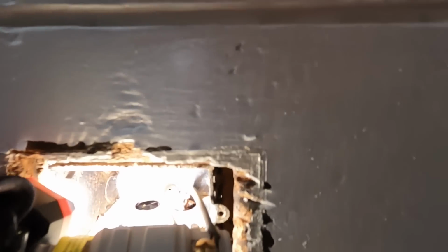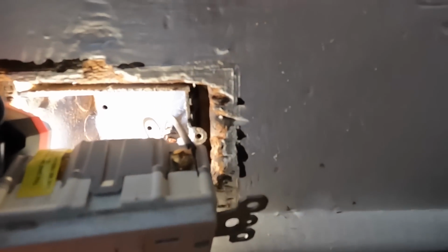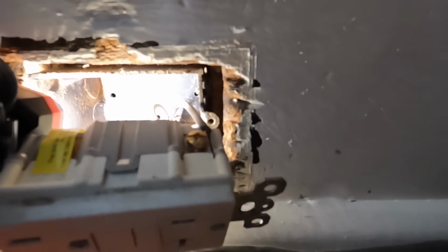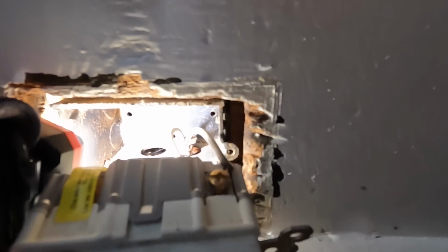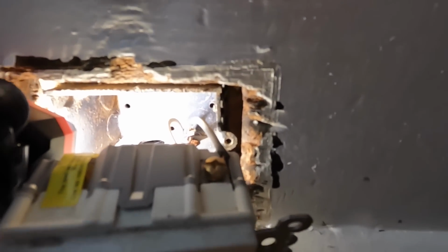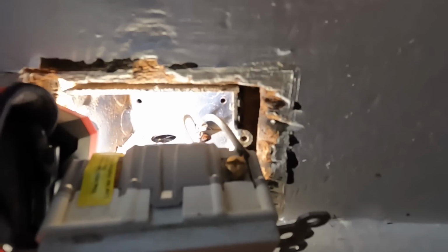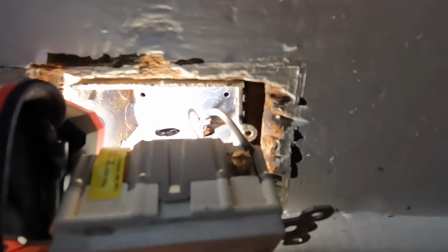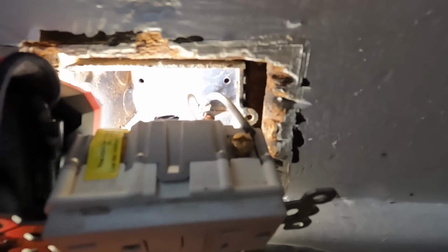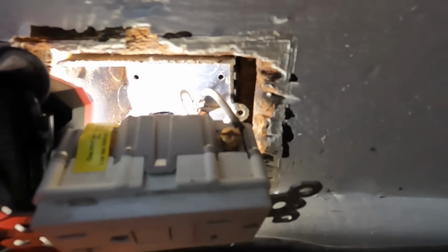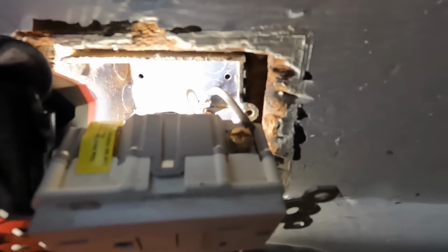I hope you could see that. But inside where that cable enters the box, see how they just wrapped the ground wire around there and did nothing with it? The intent is to bond this metal box. So should the hot conductor come in contact with the metal box while you're working on it, for whatever reason, that box doesn't stay energized. When it's properly grounded, it'll send fault current back to the source to open up the circuit breaker that the circuit's been affected by.